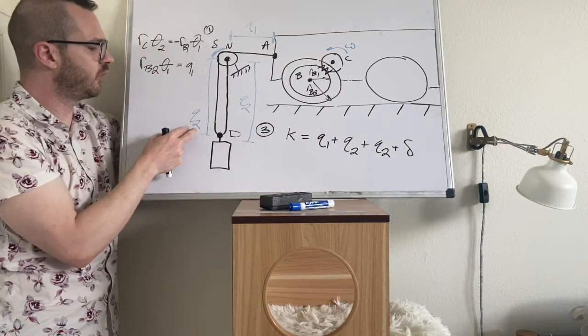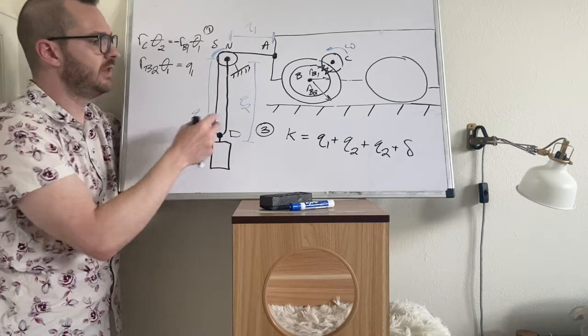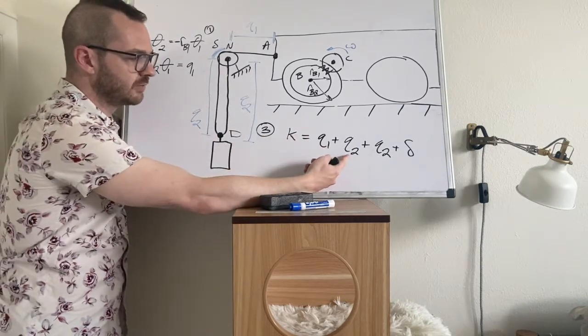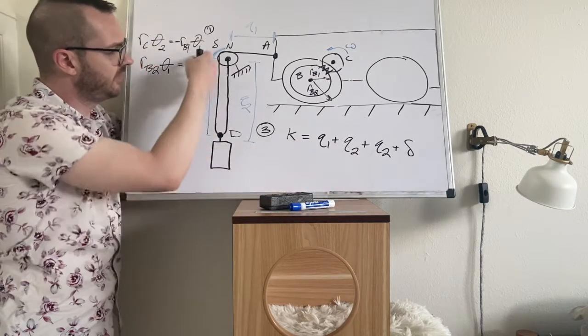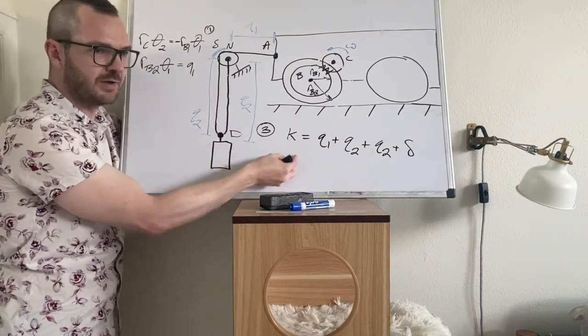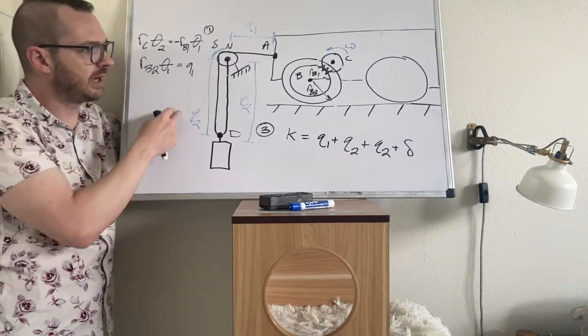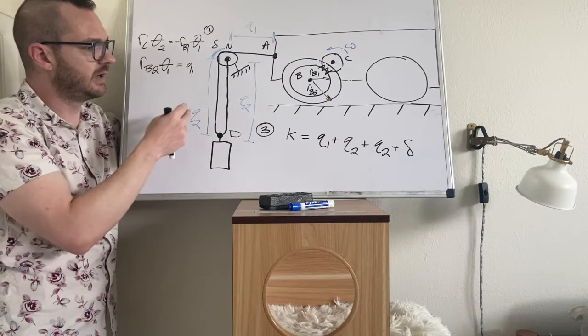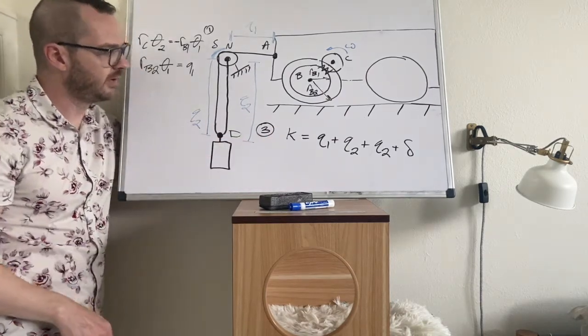If we had defined it so that Q2 had a numerically negative value, then we would have needed to subtract, negative to make it positive, because this distance is not taking away from the length of the rope, it's adding. So sometimes when you do constraints, depending on how you define your position vectors, just take those things into account and make sure all the logic is consistent.